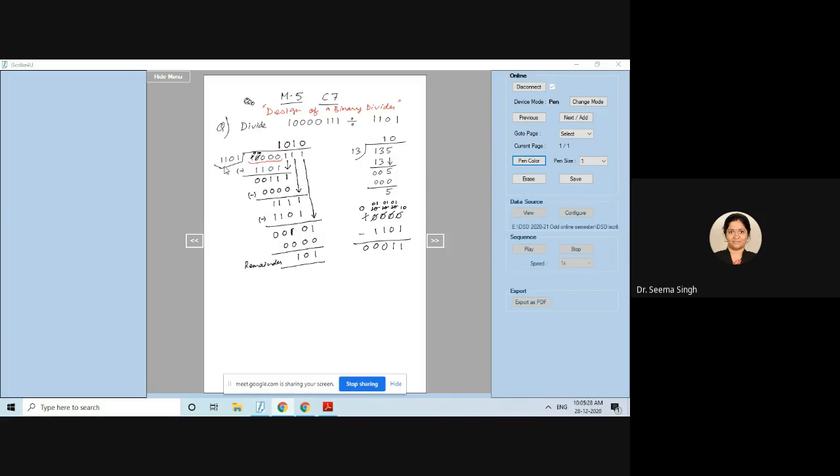So what all operations are required is, we require a subtractor operation, we also require a comparison operation, and because in binary division the quotient will be either 1 or 0, we have to see that whenever we compare and we get a smaller number as the result of subtraction, or in other words, whenever we compare and the divisor becomes big, we only shift the dividend, and it is as good as multiplying it with 0, subtracting, and this one.